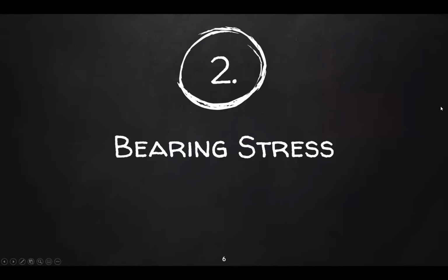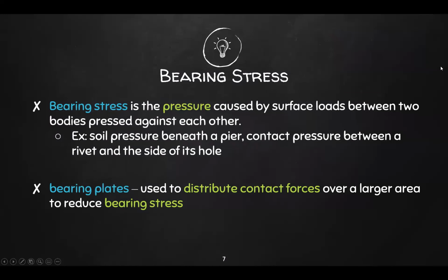The next type of stress is your bearing stress. Bearing stress is the pressure caused by surface loads between two bodies pressed against each other. For example, the soil pressure beneath a pier experiences bearing stress, and so does the contact pressure between a rivet and the side of its hole. We already talked about a rivet, right? We have a shear stress from a rivet, and another stress that it's experiencing is bearing stress. We'll illustrate that later.